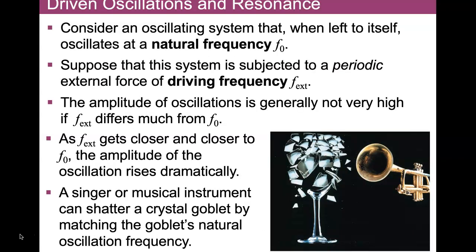An example is you've probably seen these examples of a sound shattering a glass, right? So sound has some pressure waves in the air. Locally, if you look at one position on the glass, basically the air molecules are oscillating, so the pressure of air is oscillating in some way. And if the frequency of those oscillations coincides with the natural frequency of oscillations of the glass, you can put a lot of energy in and destroy it.